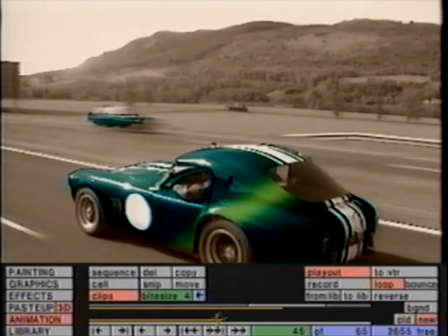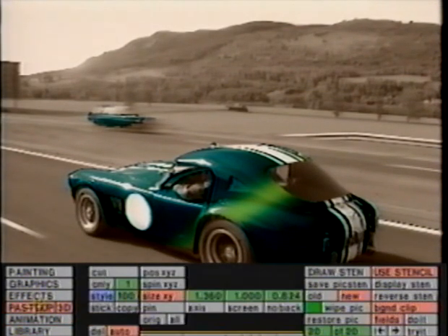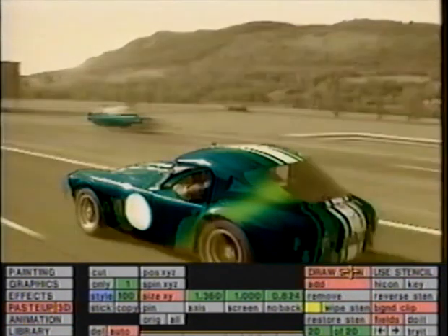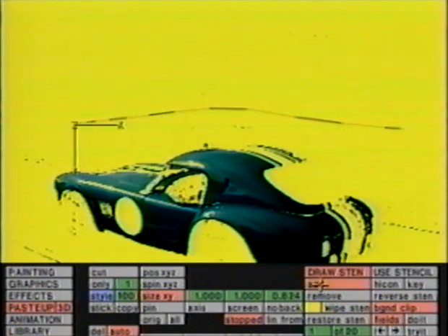To use a static stencil to rotoscope a clip, the clip stencil should be deleted from the clip. The clip stencil will still exist with the clip in the clip library. When Draw Stencil is on during paste-up processing, the foreground layer will be stamped into the existing clip stencil. This provides a very quick way of adding a tracking garbage mat to a clip stencil.